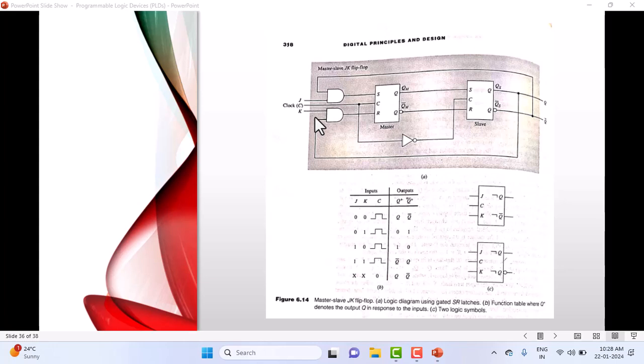Here in this case, if you assume toggle, it will keep on changing: 0, 1, 0, 1, 0, 1. If you observe the LED, it will start blinking always. Understand it? Such a mode is called the toggle mode. I hope you understood this. In detail, I have different cases, just like I showed you for the master slave SR flip-flop. I'll show you 4 different cases, but this is a summary of all the possible cases.